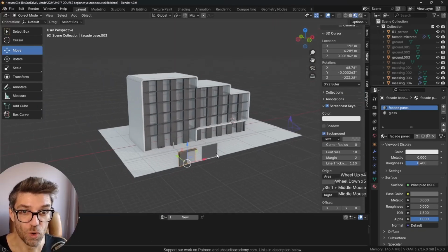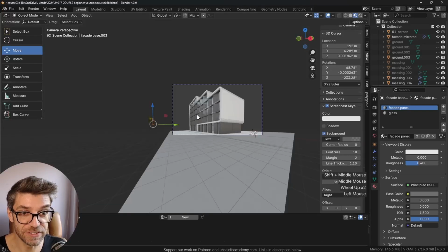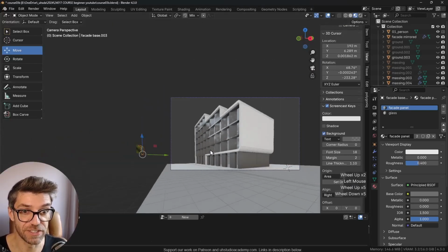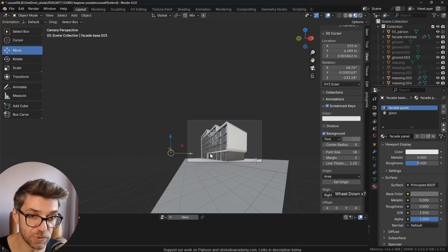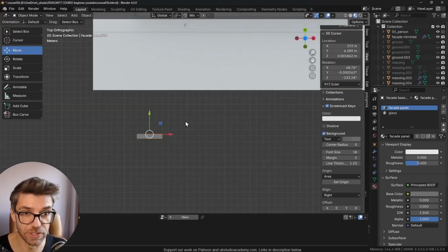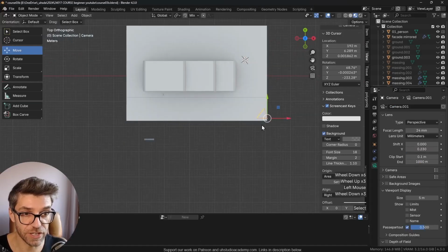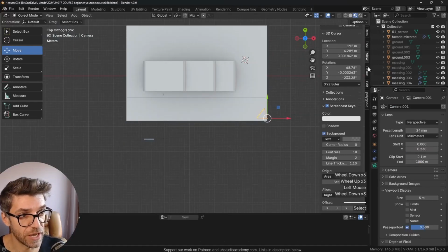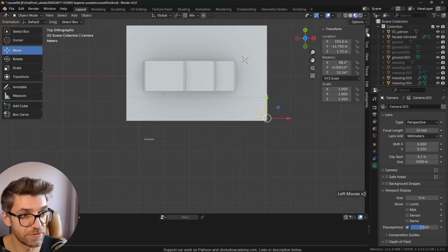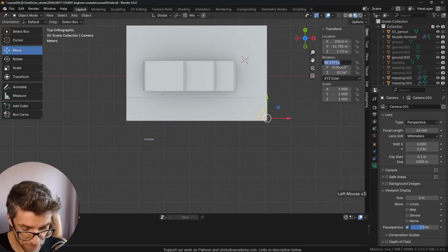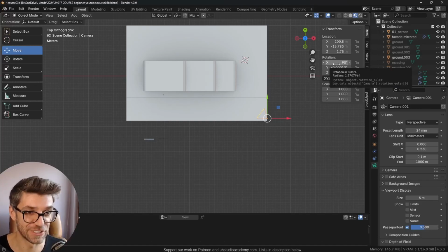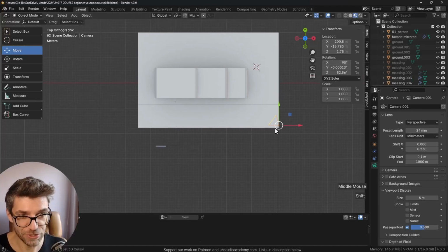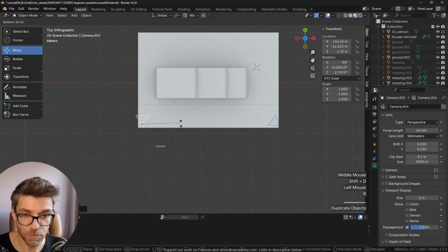Right, so one ideal solution for that is setting up a few more viewports so we can save this and build our own catalog that you show to your key stakeholders. So this camera feels like it's very slightly rotated. I don't know how it happened. I like this to be exactly 90 to have our perfect vertical lines. Okay, so Shift D to duplicate this camera and move it around.